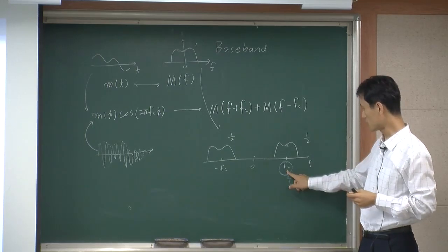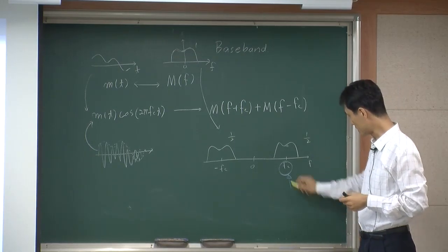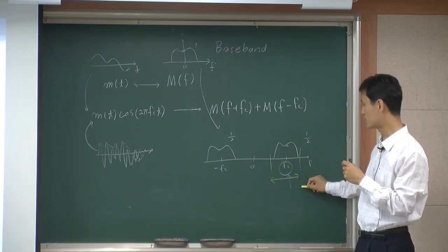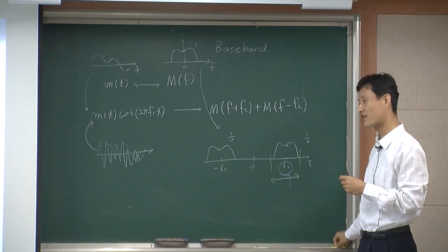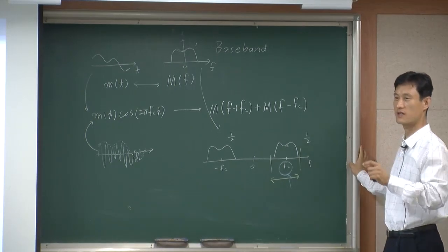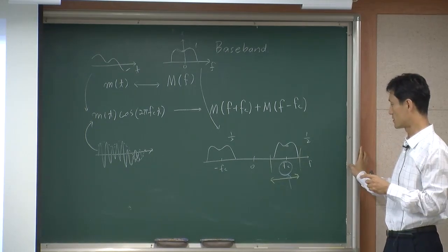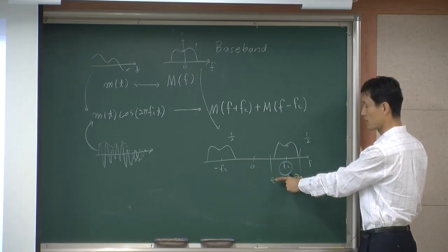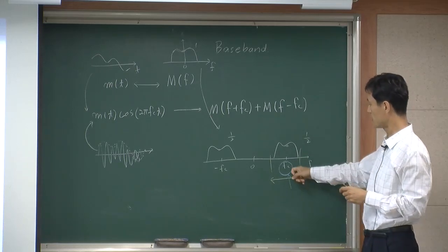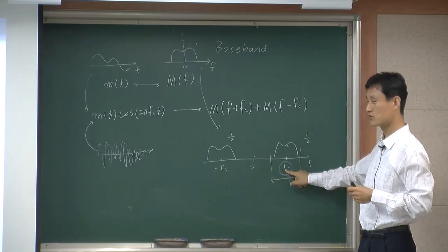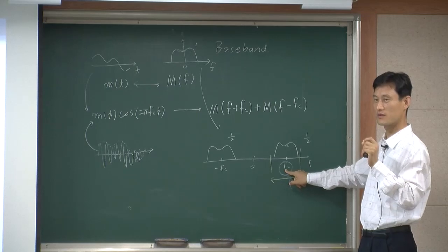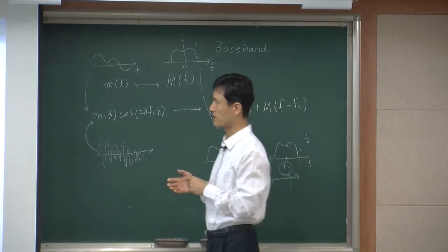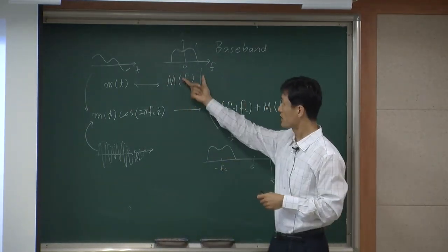So this is called the carrier frequency, and this is what we call the bandwidth, the frequency band that is assigned or given to you by the government or some organization. So you are permitted to use this for your communication. Typically this is given to you. Fc you cannot select. So 1.8 gigahertz is for your cell phone, 2.4 is your Wi-Fi.